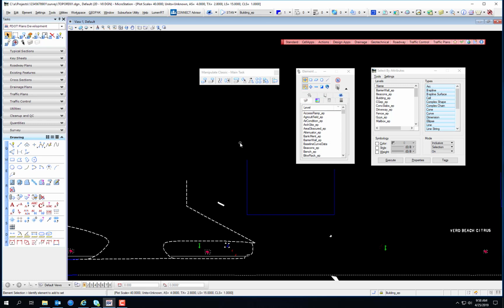It used to be that there were two separate selection tools in MicroStation. There is a selection or an element selector tool and then the power selector. And you could choose which one was going to be the default tool. That's under the user preferences. And by default, the regular selector was the default tool. And it wasn't a very robust tool. It was literally just a tool that you could select elements with.